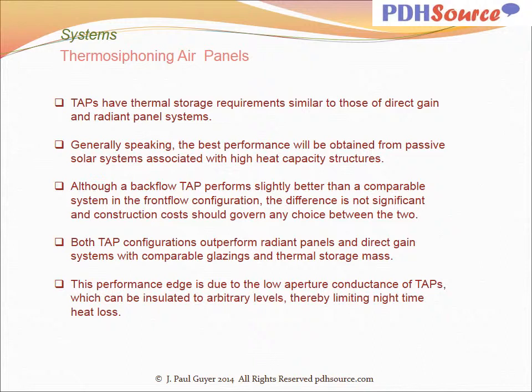Both thermosiphoning air panel configurations outperform radiant panels and direct gain systems with comparable glazings and thermal storage mass. This performance edge is due to the low aperture conductance of the thermosiphoning air panels, which can be insulated to arbitrary levels, thereby limiting nighttime heat loss.